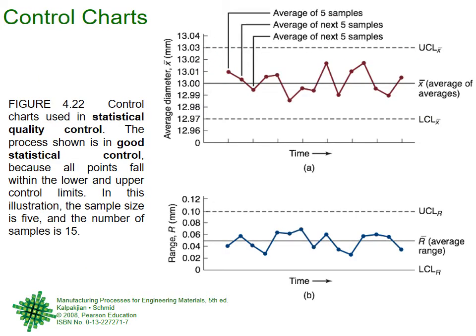That will come later on, but right now let us talk of control charts, because we were talking of control charts before, right? So this, for example, is a control chart based on x bar. So this x bar is the mean value, and every time you take a sample, say for example 5 pieces, you take their average value, it comes out to be this.